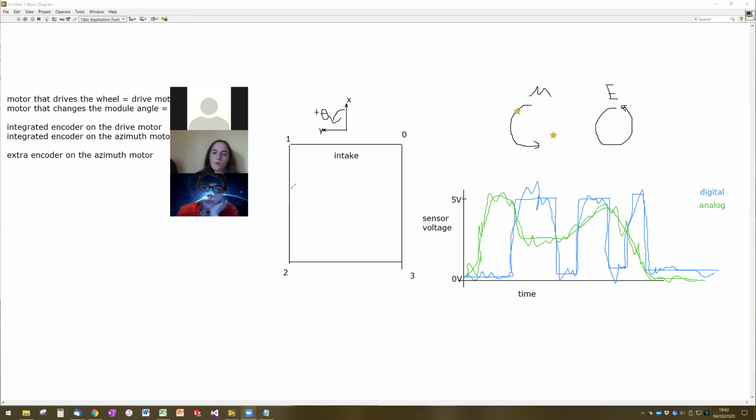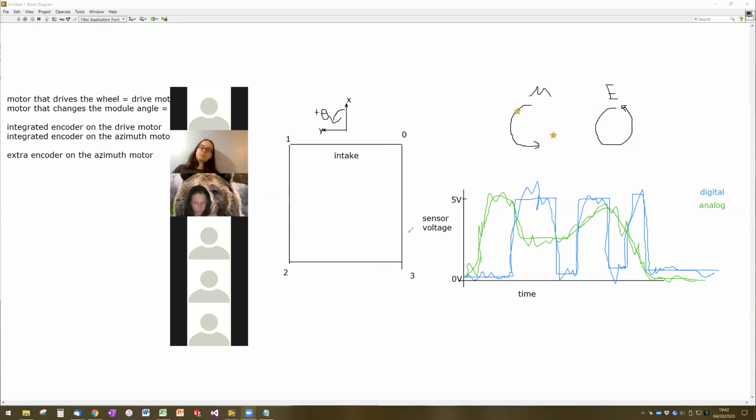One of the ways that you can fix this is, there's a number of ways. One of the ways you can fix this is with shielding the wire. Basically, you put another piece of metal around your wire so that magnetic fields induce electric current in that piece of metal and don't penetrate to the metal in the signal wire. There are very fancy ways to do shielding, which work great. We did a really simple one, which we just took some aluminum foil and wrapped the wires.